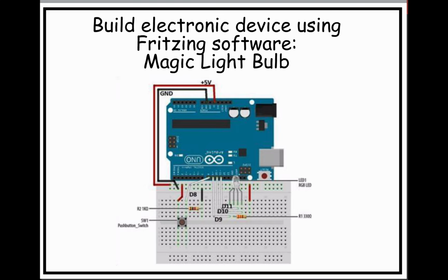If you notice, this is a little mini breadboard. The kit, meaning the Ultimate Microcontroller Pad, has a full-size breadboard. It's clear. I'm not an advocate for the clear board. Sometimes it confuses me when I'm wiring up a circuit, but some people like it because they can actually see how to lay their wires out. And also, the nice feature that I do like is it shows the construction of how the breadboard is built, so you can understand why these particular five little dots on the board are positioned the way they are, and how to really wire up a circuit without, say, creating a short circuit, meaning two devices that should not be connected. That will be considered a short circuit.